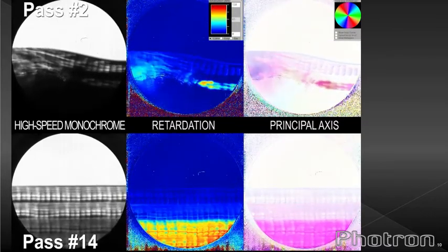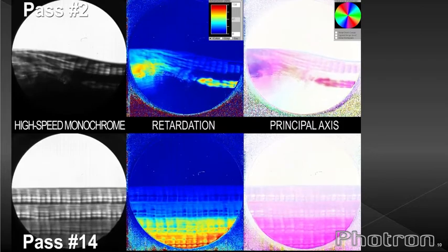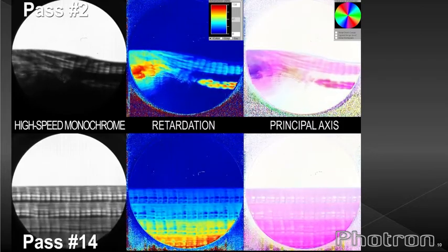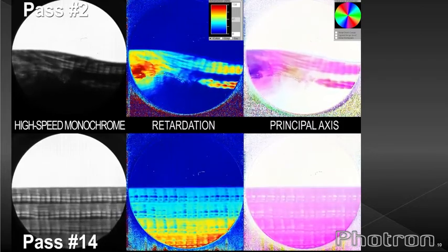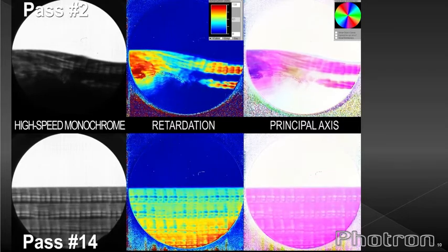Here we see three different aspects of two passes from the same NIST test recorded at 60 frames per second with the CRYSTA. The results show the birefringence changing as the polycarbonate cools. Test specifics are layer heights of 300 microns with a 400 micrometer internal diameter nozzle at 280 degrees centigrade and around 30 millimeters per second feed speed.